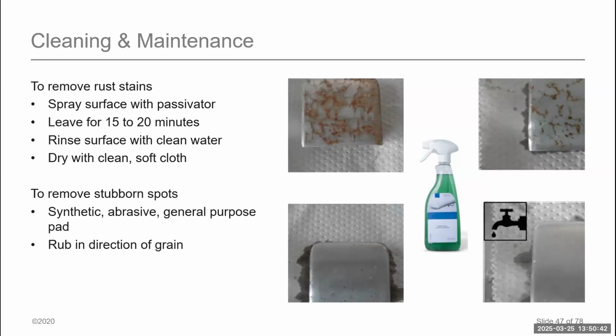Now, we need to think about the material finishes that we select in these instances, okay? We have many finishes that these can be in. They can be in satin. They can be in brushed. They can be in mirror polish. They can have powder coating. They can have wet painting. When we have an area where we have contaminants, we're going to want a mirror polish because there are no crevices.